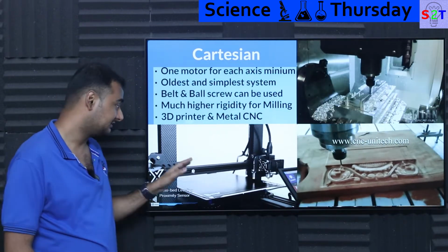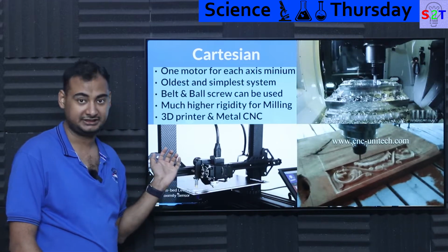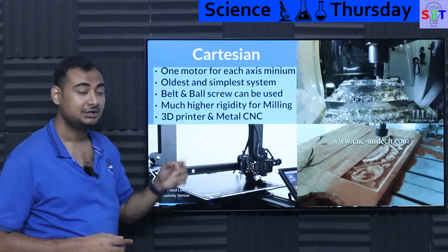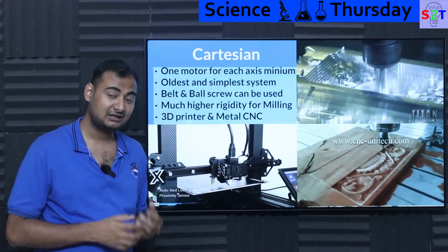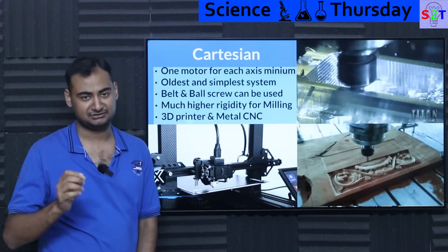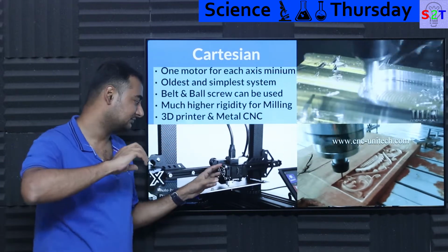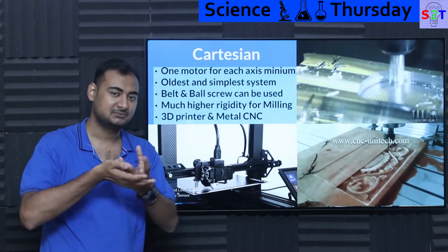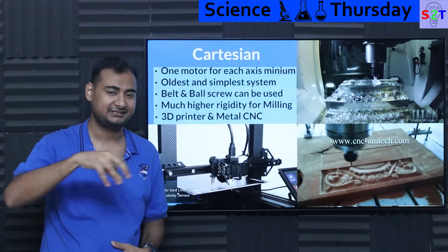Now you can have a built system, basically built-in 3D printers, but you can also go to ball screw. Now that's the interesting part. The moment you touch ball screw, you get rigidity. Now once you have rigidity, you can fight against something. A 3D printer has minimal reaction, meaning basically how much energy it has to spend to fight the filament that is coming out of it is negligible. Yes, there is plastic, yes, there is some viscosity there, but it's very negligible.